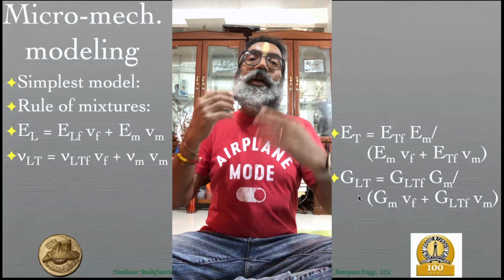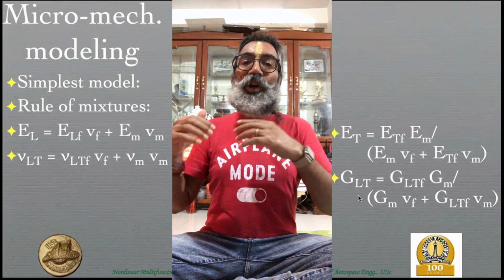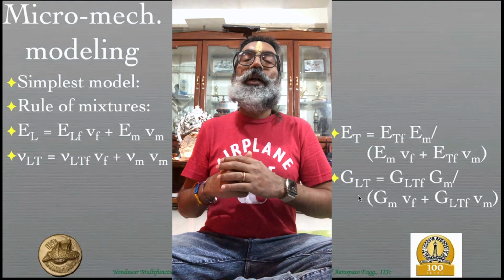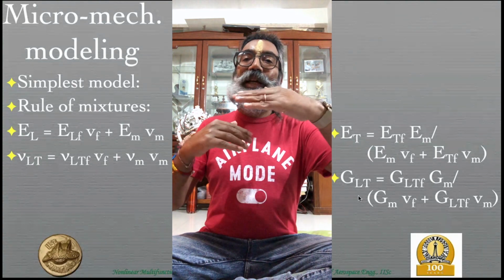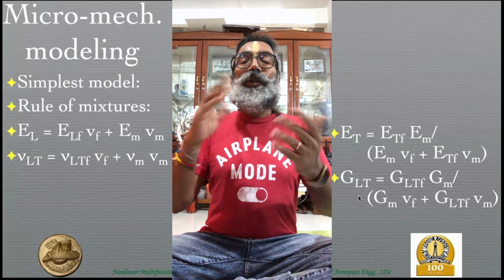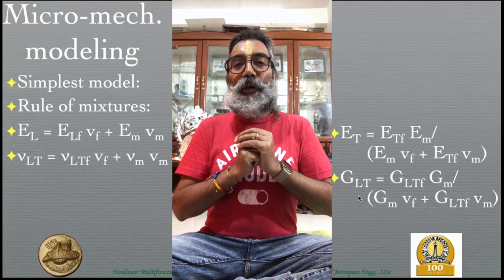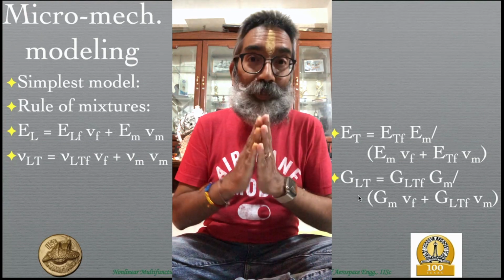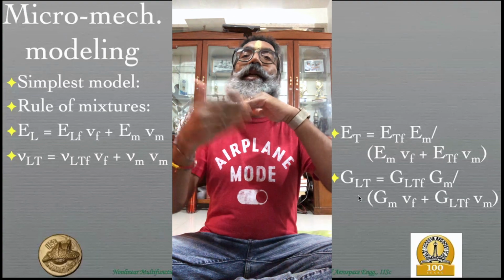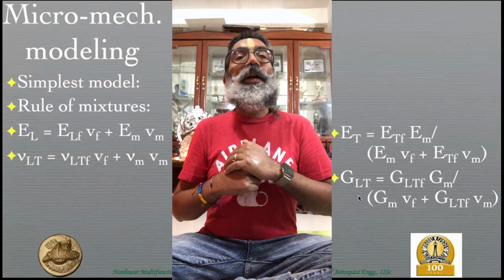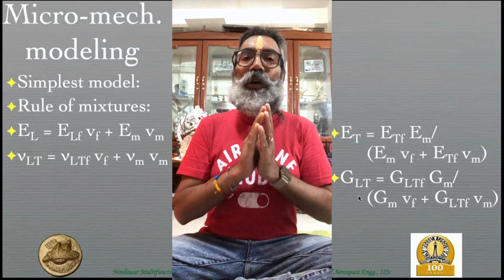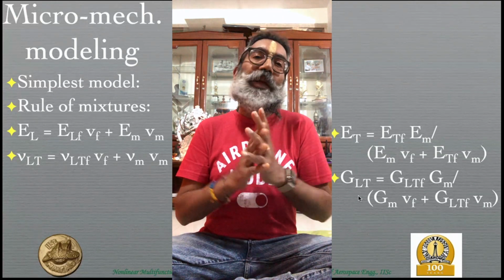It does not offer sufficient resistance, and because it's not offering resistance, it's not contributing towards taking much of that stress, and therefore all the stress is taken by the matrix. So it's pretty much like, in fact, one good approximation would be just to take the shear modulus in the TT direction as just that of the matrix. Similarly, the Poisson's ratio, and you would not be too far off. For a first cut preliminary analysis, many people do that.